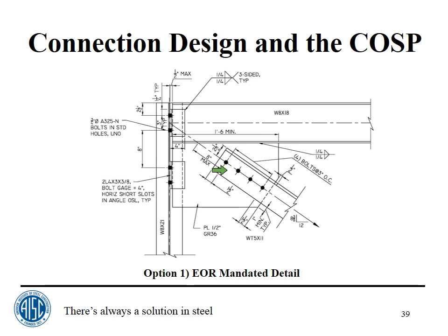We need to know the pitch of the bolts, which seems to be kind of missing here. I see I got 4 bolts with spacings, but what's the spacing? So there's something missing on this. Nope, here it is over here. I guess 4 bolts at 3 inches on center. I've never really seen it done that way, but that's fine. That's a way to do it.